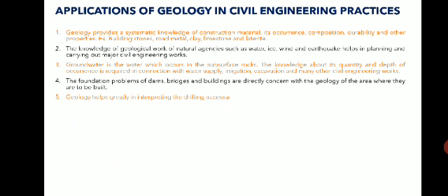So you must know at what depth what type of rock is present, whether it is hard, competent rock, or a weak or incompetent rock. All this knowledge is given by the drilling core samples. Like we drill the holes, okay, we take out the core samples of the rock, like a pipe. You might have seen, whenever borewell drilling is going on, the core samples come out. It is like a pipe, like a rod. If you study that log, it will give you the knowledge about what is there below the ground.